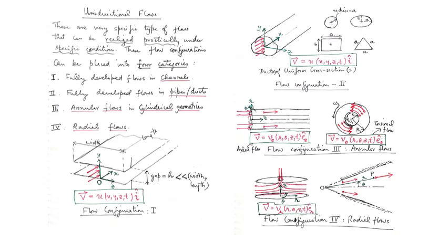So that small region near the entrance, if we ignore it, close to the inlet, then we can approximate the flow as a purely radial unidirectional flow. So the velocity vector V is now represented with a radial component Vr Er cap, and again I allow it to be a function of all space coordinates r, theta, z and time.